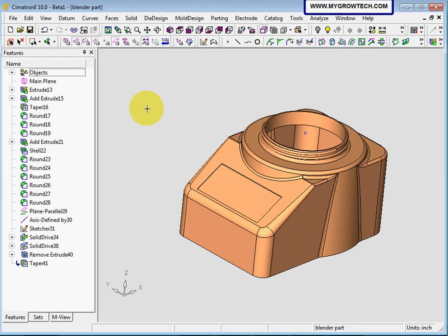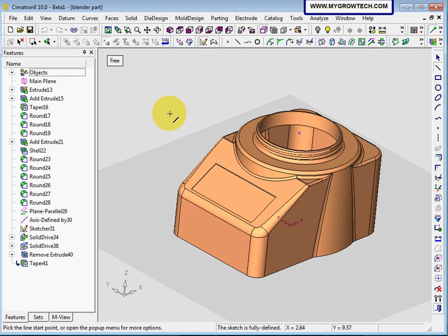Next, I'm going to create a sketch on the XY plane. Select sketch, and the tandem plane, I already temporarily hid it away. That is okay. If you just want to select the XY plane, you just press the middle button of the mouse. The default plane of the sketch is XY. Press middle button of the mouse, and the default plane, the XY plane, is automatically selected.